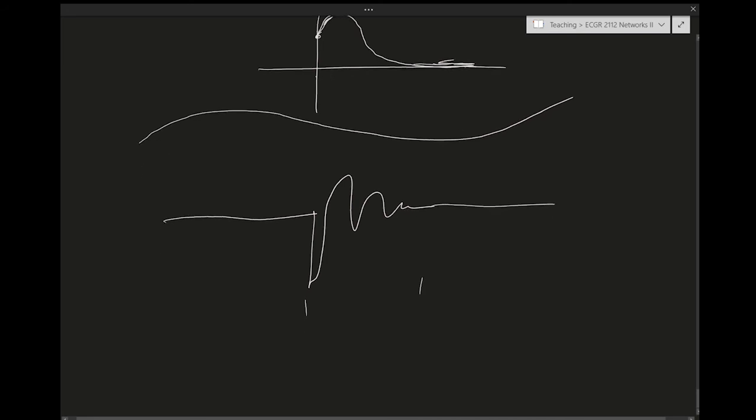We have our method of analyzing those transients, where we use the steady state before the transient to figure out where the circuit is, and then use that as the initial condition for the transient to solve for it, and then we figure out the steady state after that transient. This method allows us to analyze a lot of circuits under a lot of transients.